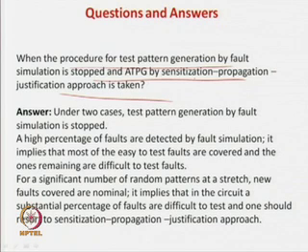The stopping criteria is when you find that, applying random patterns, the number of new faults being detected is very few, or sometimes even 0. Initially the number of faults detected will be, say, 10, next random pattern 12, and then random pattern 8, you keep on doing it, but after some time you will find that the number of new faults detected is 0 or very few. At that time you can say that I have to stop because adding random patterns is not helping me in any way and I have to go for the sensitize, propagate and justify approach.